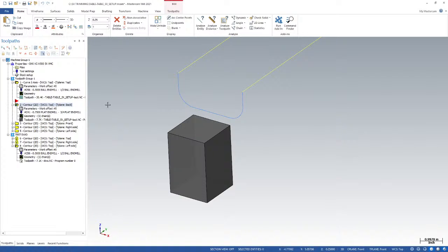There is no rotary angle. All we have is vector information, and we use linear algebra, matrix math, vector mathematics inside the post processor to resolve the difference between the z-axis vector of the WCS and the z-axis vector of the tool plane in terms of a 3+2 toolpath, or we look at the vector information in a 5-axis toolpath, and that format is completely different from the 3-axis format.